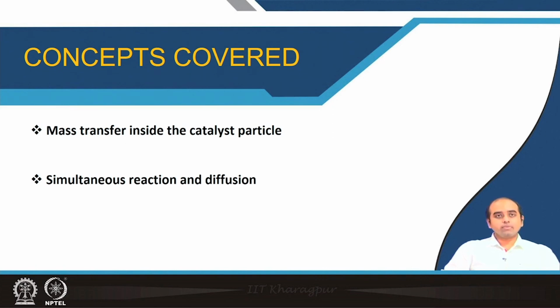The intraparticle effects are important, or let us say they are dominant, when the rate of reaction at the surface... This is something which we have already talked about in the last class when we tried to model the packed bed reactor. We said that the particle surface concentration, which acts as the sink term to the main equation, is essentially governed by the particle level dynamics.